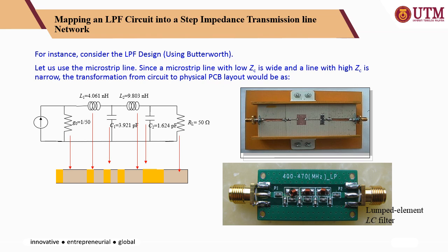Okay, next, another practical implementation of filter design. Again, another low pass filter, for Butterworth. The first step is to get the circuit realization from calculation. Then you get the filter order number. Then you determine the normalized elements or components in your filter circuit, and then put the design into your simulator.